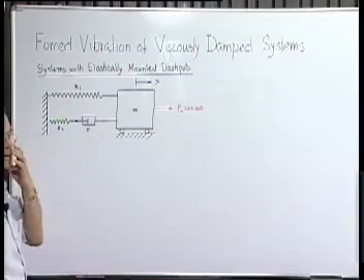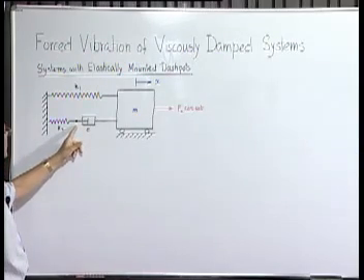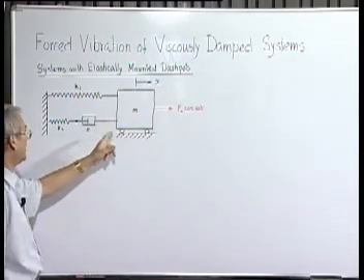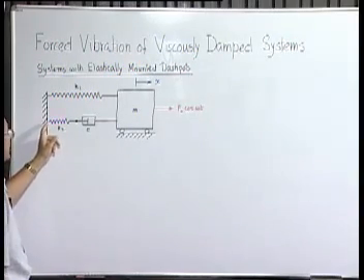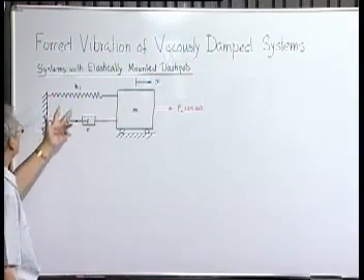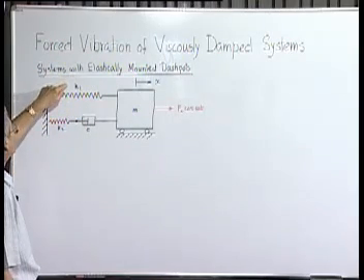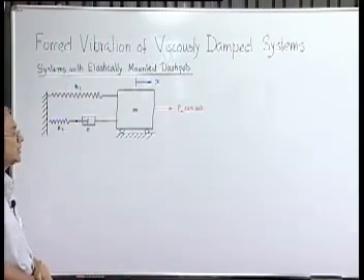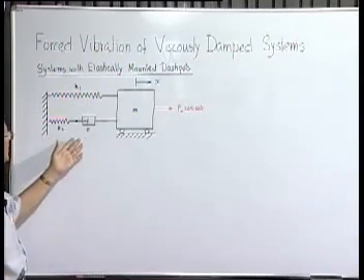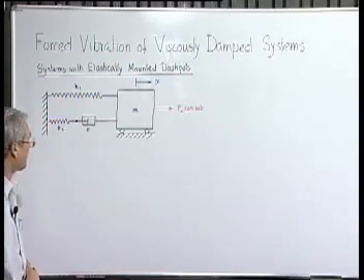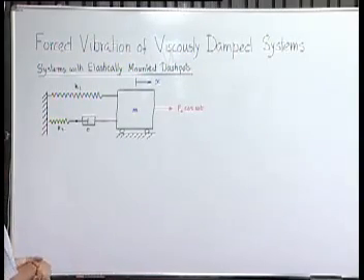So, our problem is this, that we have a system where now we find one end of this dashpot is connected to the body, but the other end is connected to a spring whose other end is connected to the foundation. So, now there are two springs because the dashpot is mounted elastically, and obviously therefore two spring constants. So, we call the spring coefficient for this one as K1 and the coefficient of stiffness for the other spring as K2, and C and M are there. Now, first let us try to see what will be the equation of motion.